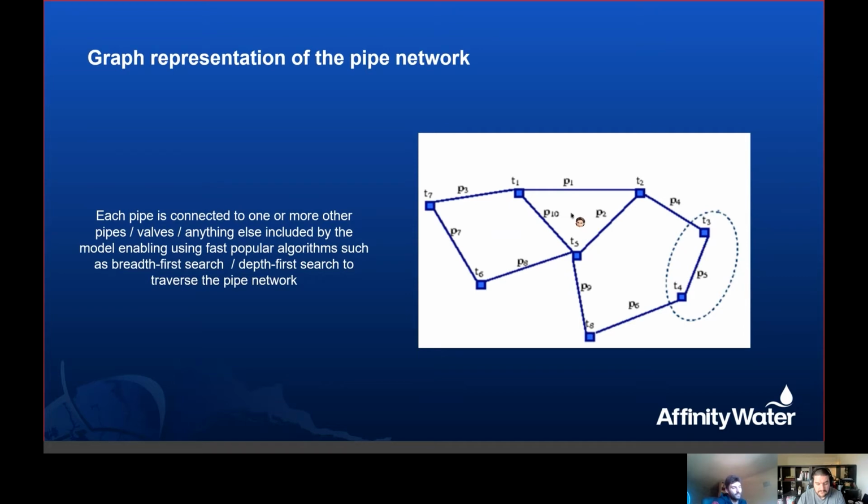They're trained on previous burst data where we find out the earliest point where a leak or a burst event is obvious, and the models therefore find that point in the future where the operation teams look at and react in the earliest possible stages of bursts. These are, as I mentioned, classification models. There are about 20 dimension models, and the main technique used to model them is XGBoost, extreme gradient boosting.